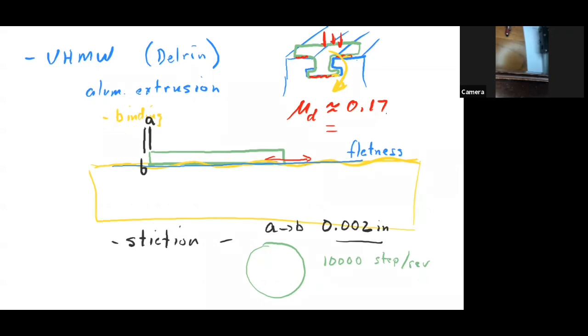News flash. You never did a single microstep in your microstepper. What happened was you had some friction in the bearings, not much, but you had a tiny bit of friction. And as the rotor magnetics moved 1 microstep, the rotor itself didn't necessarily move 1 microstep.